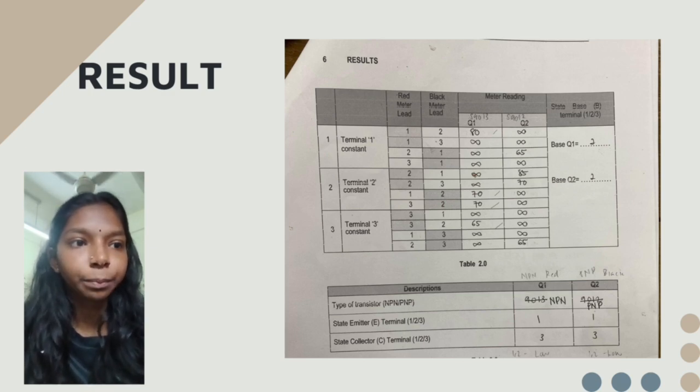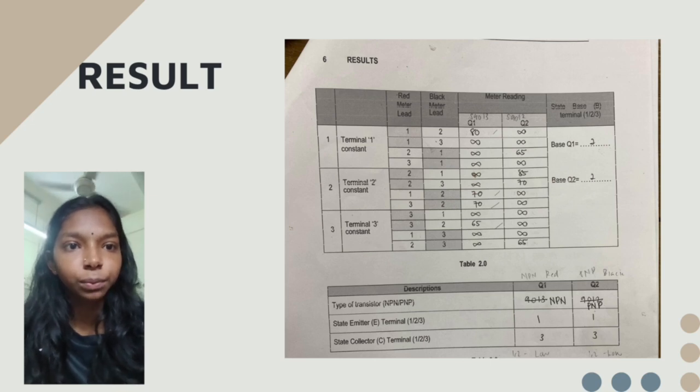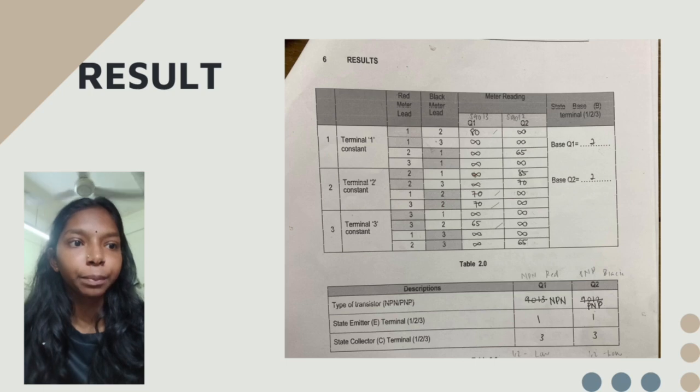The conduction behavior is that Q1 behaves like an NPN transistor because it conducts when the base is positive relative to the emitter. Q2 behaves like a PNP transistor because it conducts when the base is negative relative to the emitter.